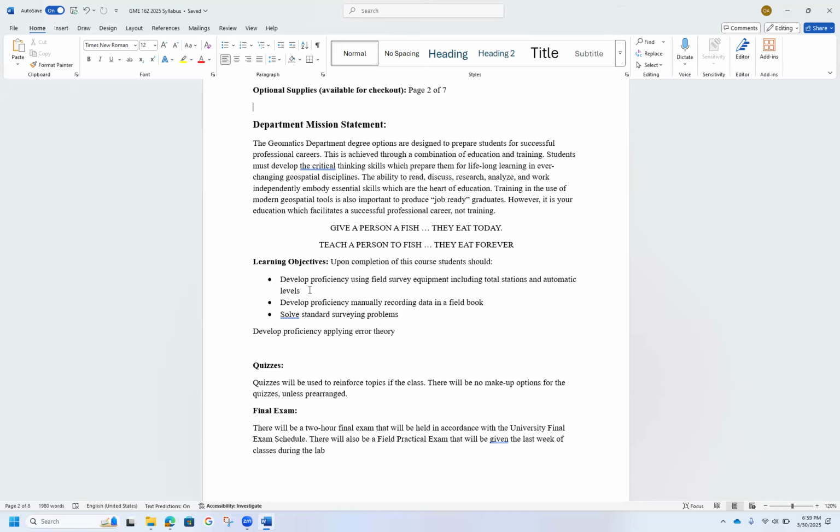But they don't know how to do the field work to set up the whole control network, to run a traverse, to run a level loop, to run the data collector, to upload and download that job file, to manipulate the data how it needs to be, to understand what the fixed points on a traverse are and why they are so important.